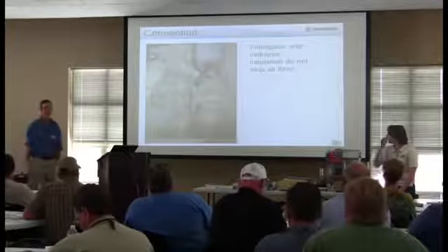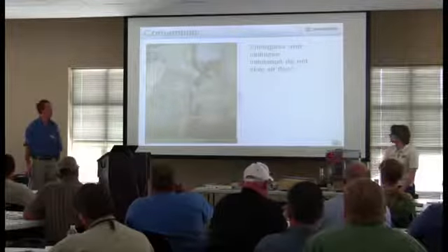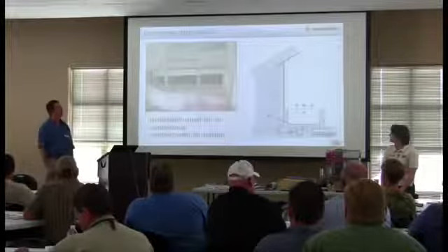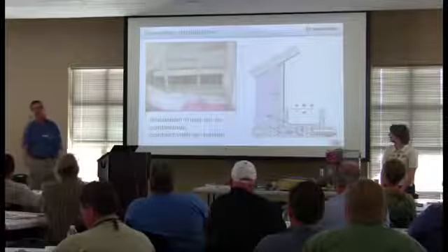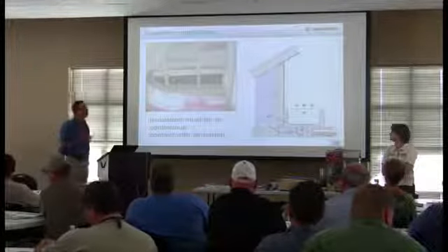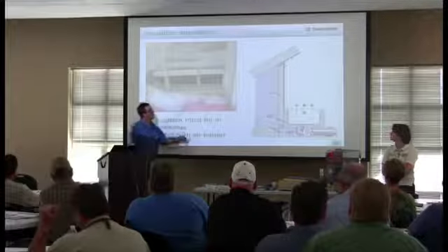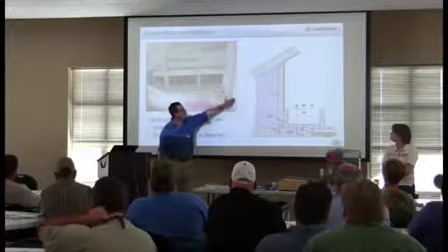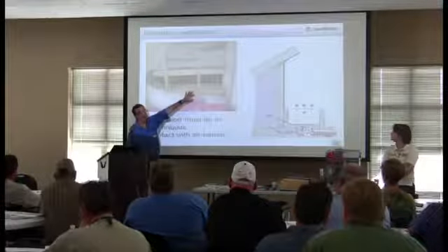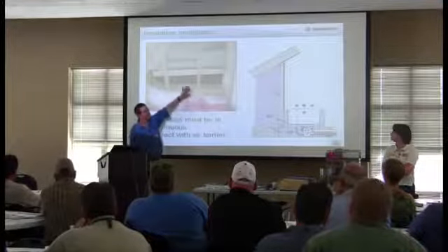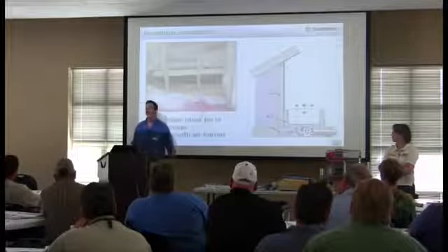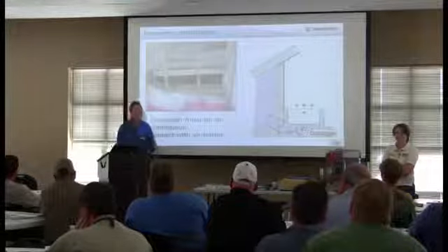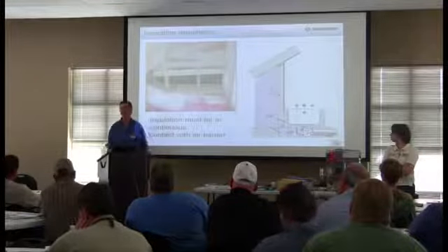Yeah. So insulation is a great product, but it doesn't stop airflow. You're getting that natural warm air rising effect in the winter, and a lot of energy flowing out. Here's another example of where the insulation was run, but there was no air barrier on a knee wall. On an attic knee wall, and in this case, this is the access door to the knee wall. This homeowner was very uncomfortable, but they survived the summer. My guess is they had a grossly oversized air conditioner. But when winter came along, it just got too darn cold.